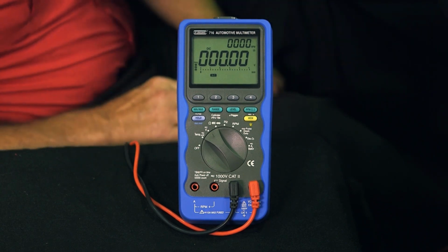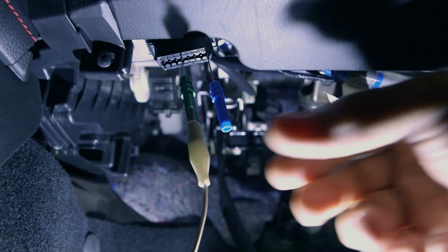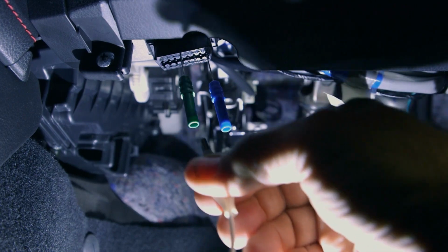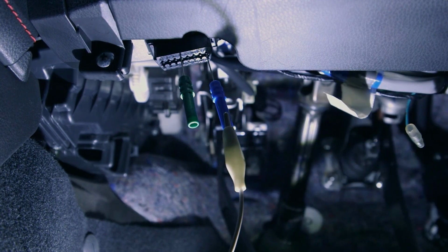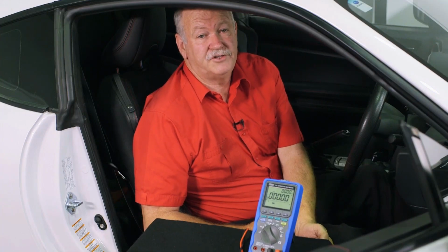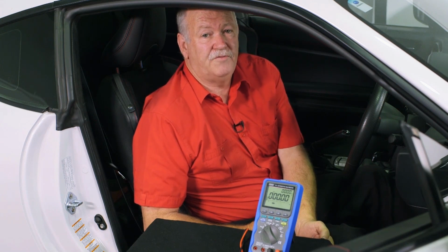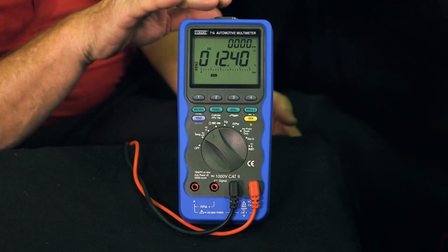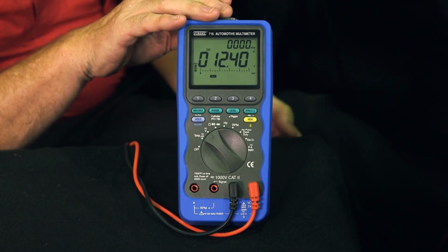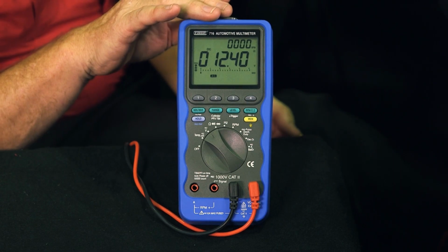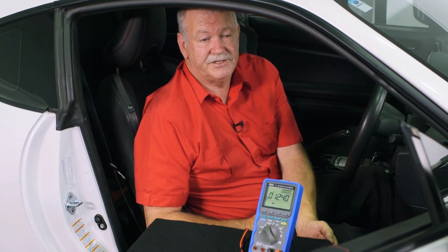So the next thing we need to test for is a short to ground. I've moved the multimeter lead from pin 4 to pin 16. This time we're looking for a short to ground. If we see 12 volts on our meter, that would indicate we have a short to ground. So let's have a look. And sure enough, we've got battery voltage there or 12 volts. So we've got a short to ground on our 5 volt reference wire. That's our fault. If there was no short to ground showing and there is no 5 volts, the problem is we have an open circuit on our 5 volt reference wire.